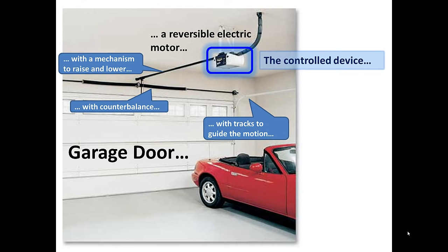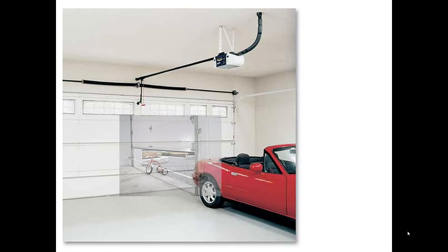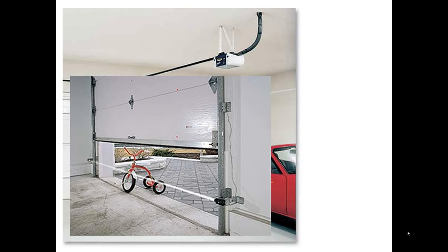In these modern times, safety of course is a big issue, especially in the United States where OSHA rules. So what can we add to make this residential device safer around children? Anyone that's dealt with a modern garage door opener knows there's a safety photo eye that is a through beam type photoelectric device that detects anything that is blocking the door from closing. And you want the beam high enough so if a person happened to be sitting there, or kind of half laying down, the beam would still be blocked and the garage door would not come down on the person.